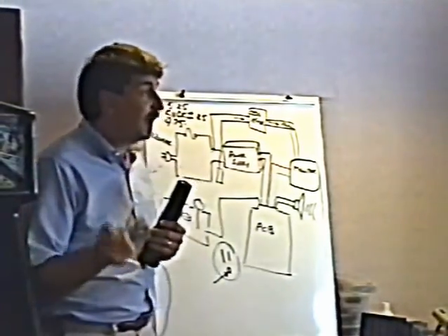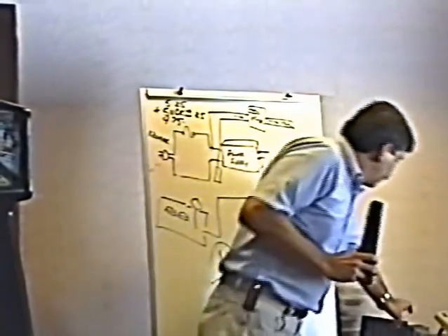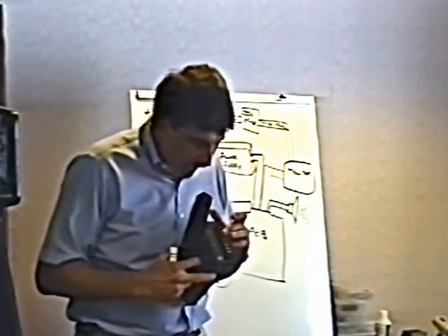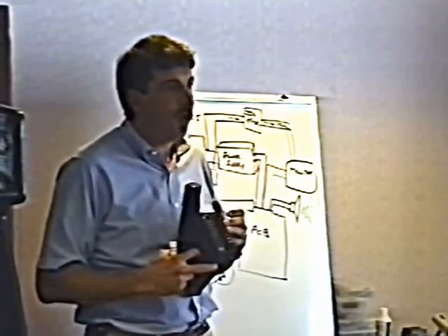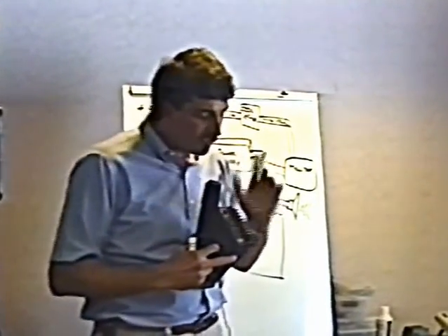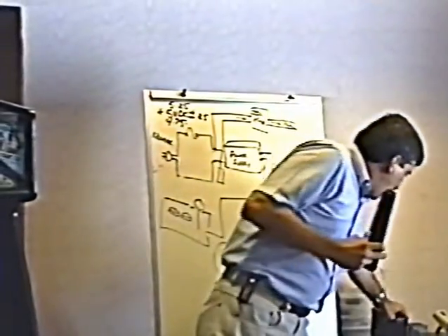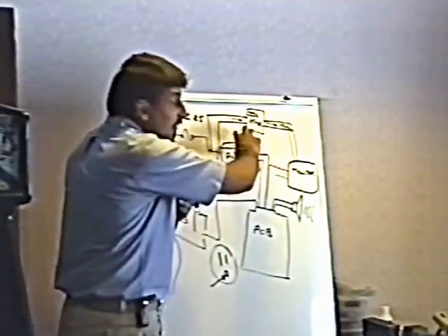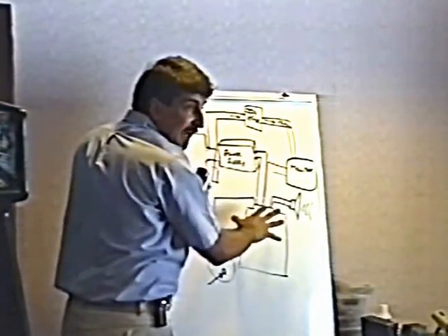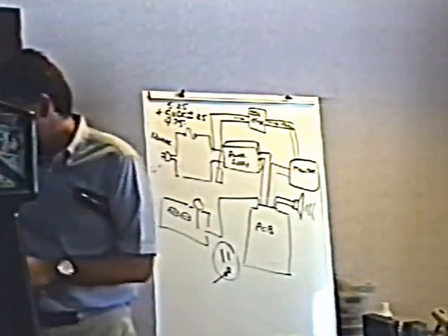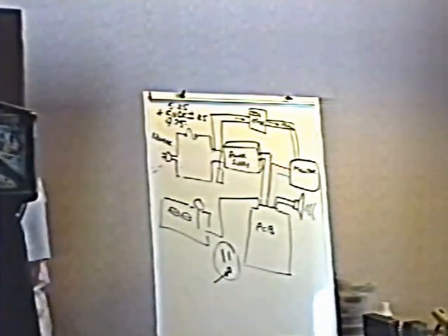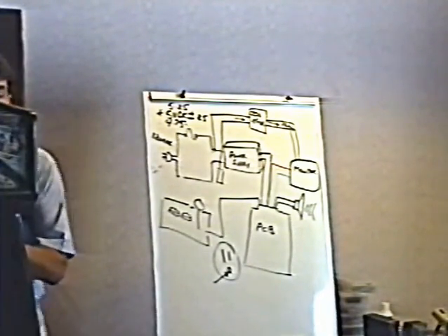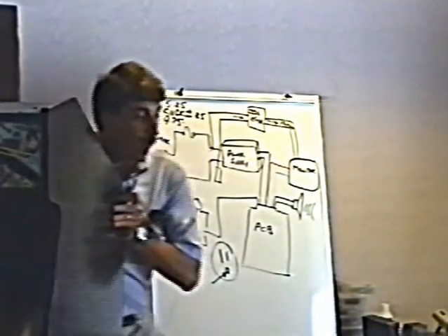But where the heck are you going to check the voltage? Well, the logical place is the same place you checked it before. You go, well, I'll just put one meter lead here on ground and the other on plus 5 and adjust it to 5.1. Not even. And the reason why not is that by the time the current gets out of the power supply, through the wiring harness, through the connector, it's real easy to lose a few tenths of a volt. And since the voltage is so critical, it's very important that it's 5.1 volts on the logic board.